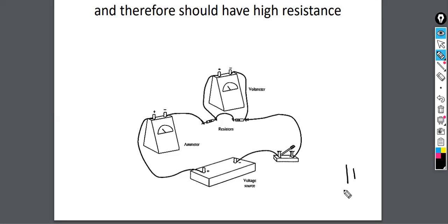The other symbols we've seen are two open circles like this, which you label, and the circuit gets connected like that. Or you can just use lines like this. Sometimes it is a battery of cells, so it'll look like this, and that's saying there are a lot of batteries here, but this is still negative, this is still positive. You can wire up batteries so that they cancel each other out. If you do positive to negative, negative to positive, you have a 1.5 volt battery and negative 1.5 volts, and you basically cancel out the voltage. I don't know why you would want to do that, but it is possible.